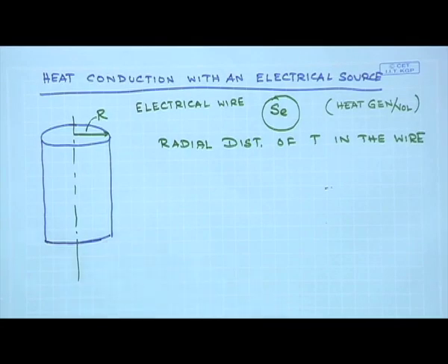So, the algebraic sum of heat in, heat out and the heat generation must be equal to 0 at steady state. And the same way as for the case that we have done for momentum transfer, the trick to choose the smaller dimension of the control volume is to realize in which direction the temperature is changing.